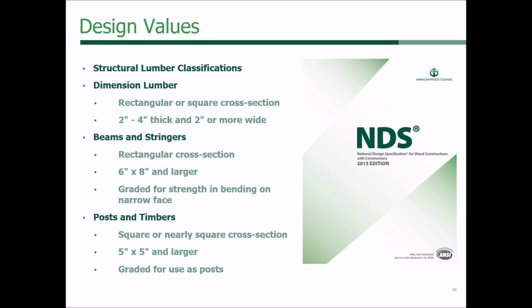One of the things that I did not understand very well when I first started designing with timber is the distinction between dimension lumber, beams and stringers, and posts and timbers, and that's important because they have different tables. Dimension lumber is basically anything 4x4 and less.